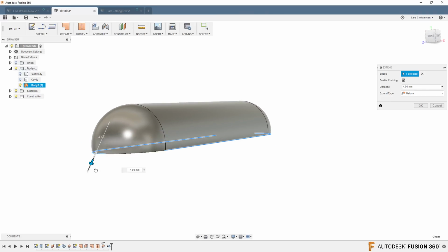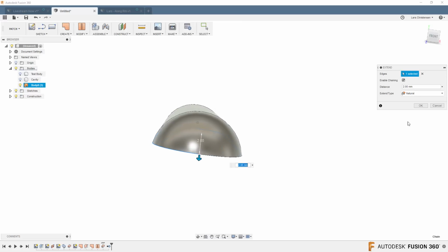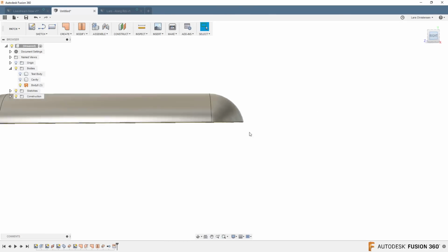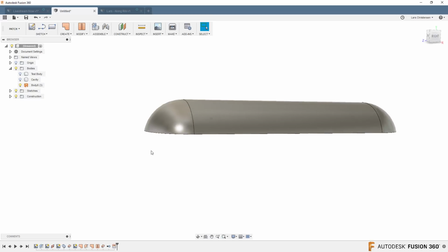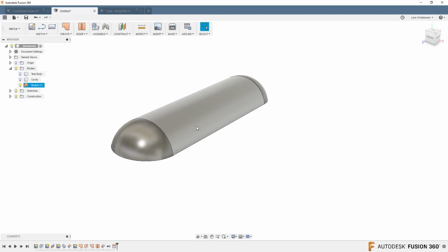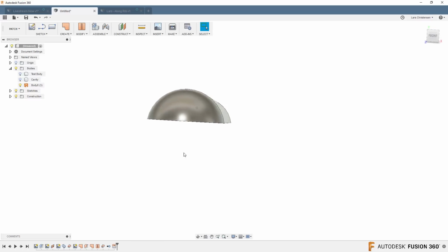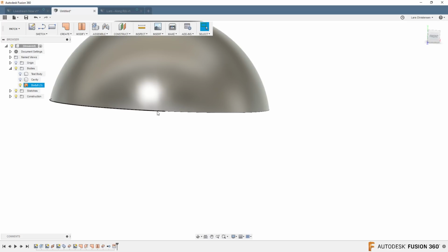I don't know how far down. You can go pretty far, but you can see it's going to start collapsing in on itself. Maybe down to about 2. Hit OK. Now, one thing that is important to know, especially with surfaces, is that anytime you're working with surfaces, they have to be precise. Because this surface has both been offset by 1 millimeter and extended, I don't trust that these edges are actually 100% anymore. If we zoom in, you might be able to see that they're starting to break down. That's not even the center.